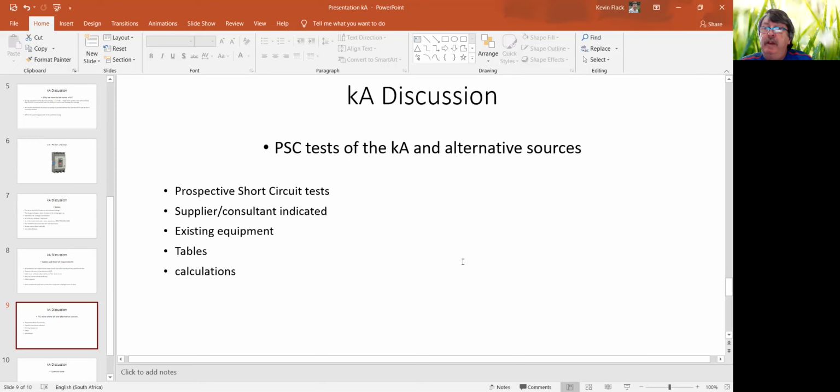Mechanical strength on cables, we've probably skimmed over, this should have been the other slide. In terms of the actual kA withstand, it is approximately the square millimeter withstand level. So a 25 millimeter square cable is around about 25 kA. As I mentioned, the 1.5 squared would be a waste of time with a 30 kA short circuit. And of course, you can do the calculations. Nothing stops you using calculations from first principles.